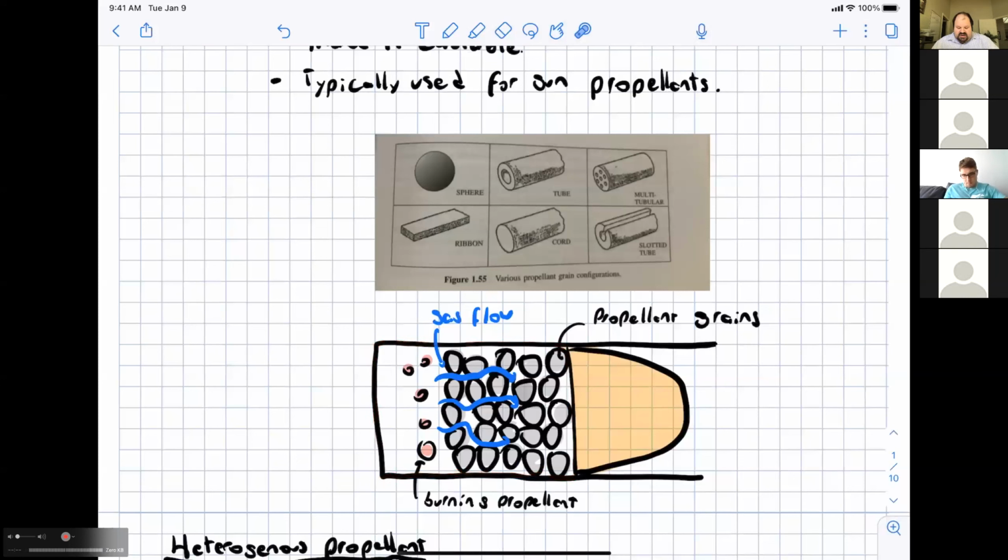So they need to very carefully tune the energy release rate of the propellant as a function of time, so as to maximize the efficiency of the round in a safe manner, and avoid the consequence of needing to make the barrel thickness like 6 feet thick to be able to take those kinds of pressures. We will discuss internal gun ballistic models, but they are very complicated.